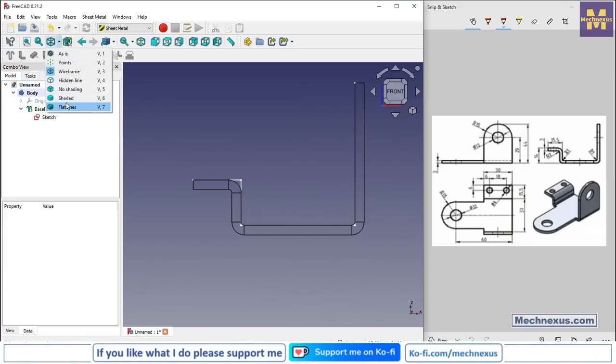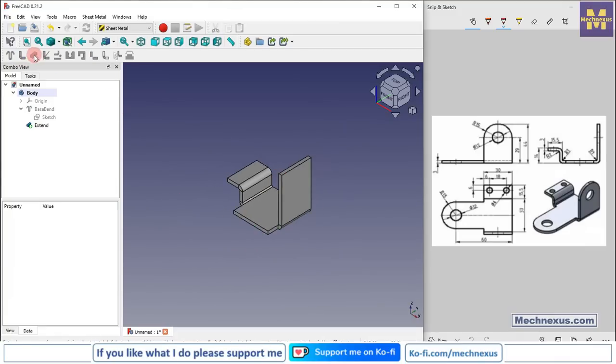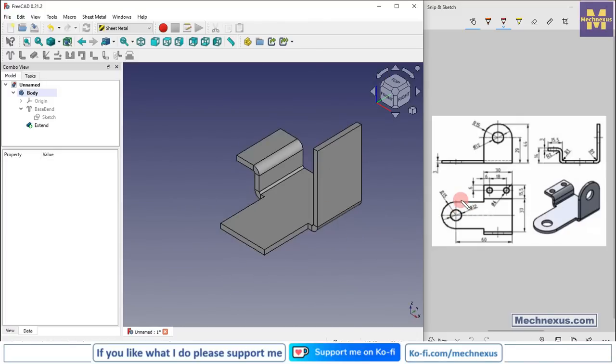Now we will switch to the flat lines, and on this sketch press 0 for isometric, and now we will extend this face. So we will select this bottom edge and click on extend, and now we will modify this extend. So this extend length is of 30 mm, and here is a gap on both the sides. So we will give the gap of 2.5, gap 1 and gap 2 of 2.5. So you can see that the gap has been created because we want this dimension 30 mm.